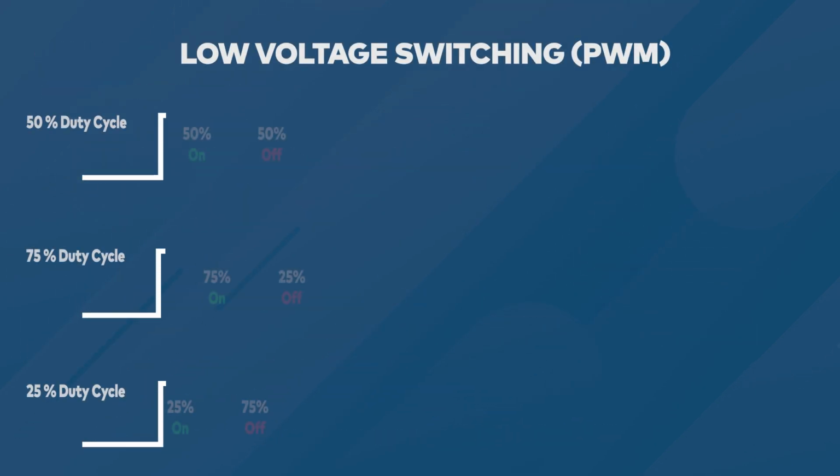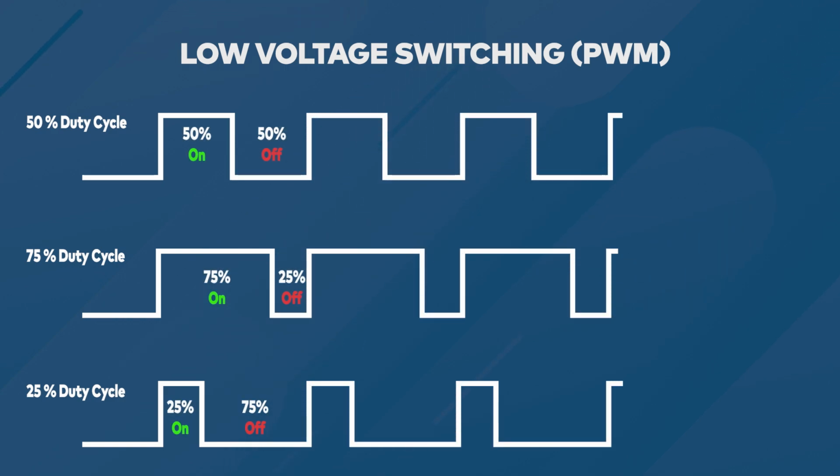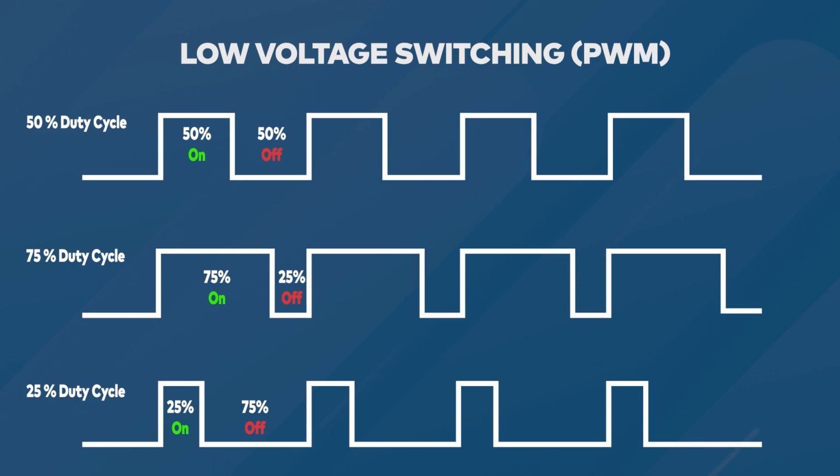Light-emitting diodes, or LEDs, being diodes, are essentially electronic switching devices which also emit light. They do not have a noticeable dimmed output and operate at very low voltages. In order to appear to dim, an electronic circuit is used to deploy pulse width modulation. This will turn the LED on and off in rapid succession, much faster than the human eye can detect. The ratio of time on and time off will create the appearance of a dimmed output. PWM controllers will require a constant electrical input in order to operate correctly. This controller may receive lighting level instructions remotely via control voltage or control signal.